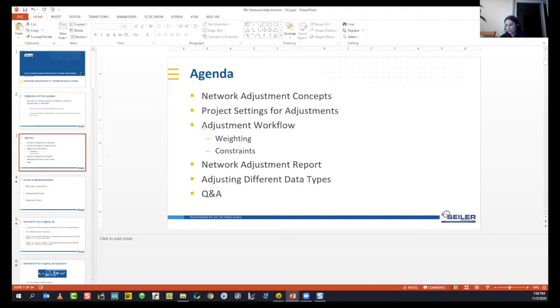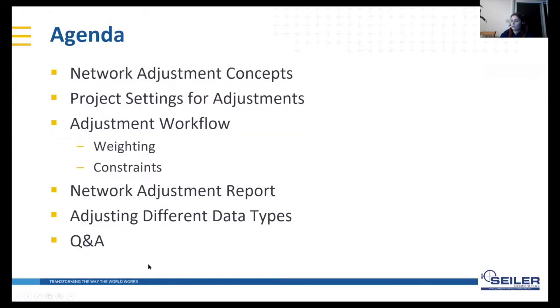There are different types of network adjustment. One of them is minimally constrained network adjustment, and another is constrained network adjustment, where we include more points. We will start with the minimally constrained network adjustment, just trying to change the settings of our first point. Okay, that's better.